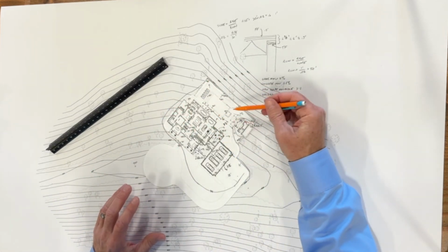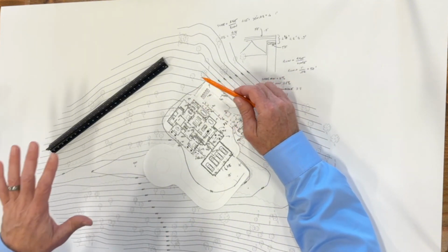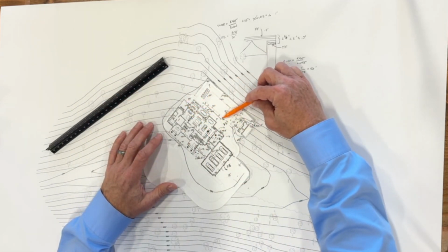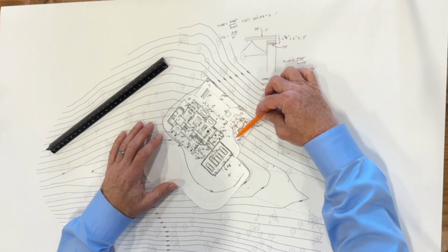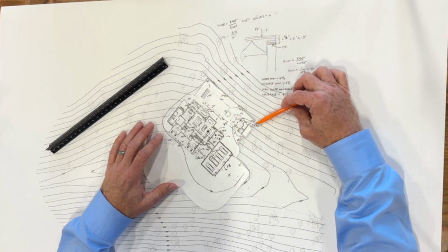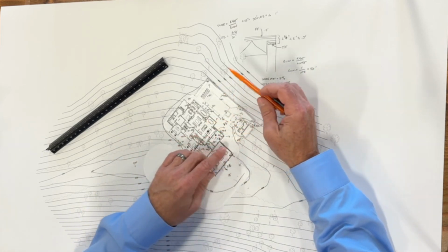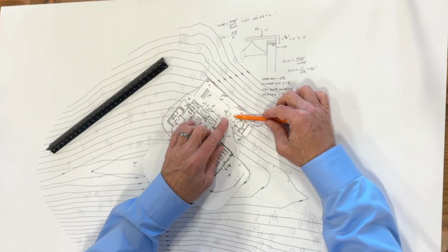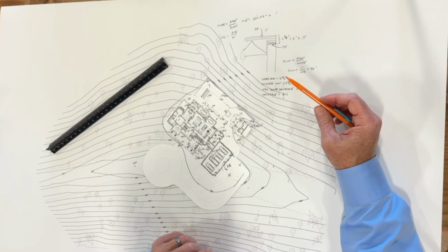So what also happens, notice, is these two low spots on this whole deal. Say it just had a hellacious rain and this whole thing started filling up with water, and then always allow for the drain to plug. So if the drain plugs, the water is going to go up and it's going to go whoop, right through these two 939.5s, right? So this is the overflow swale of the whole deal. Some water will go this way to the 940, but over here where there's further to go, it'll go right there. That makes sense? Okay.